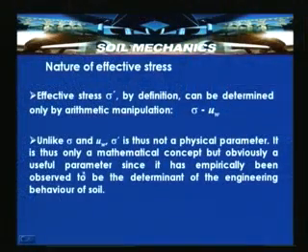It is only a mathematical concept, but obviously a useful parameter, since it has been empirically observed to be a determinant of the engineering behavior of the soil. Though it is obtained by arithmetic manipulation from total stress and pore water pressure, it determines many engineering properties of the soil. So this is a very important parameter in soil mechanics.